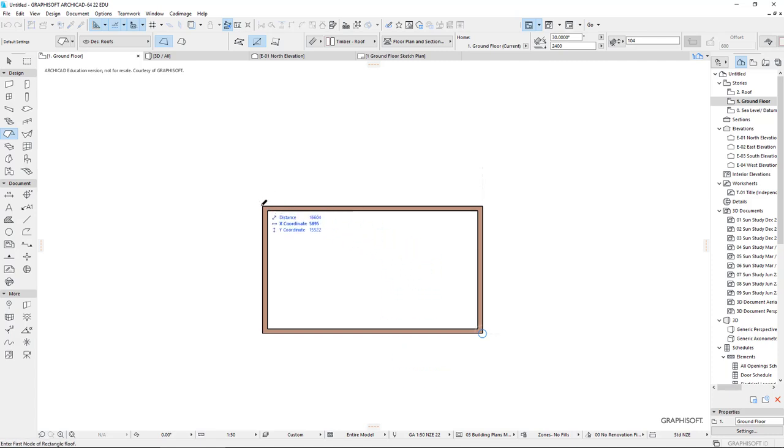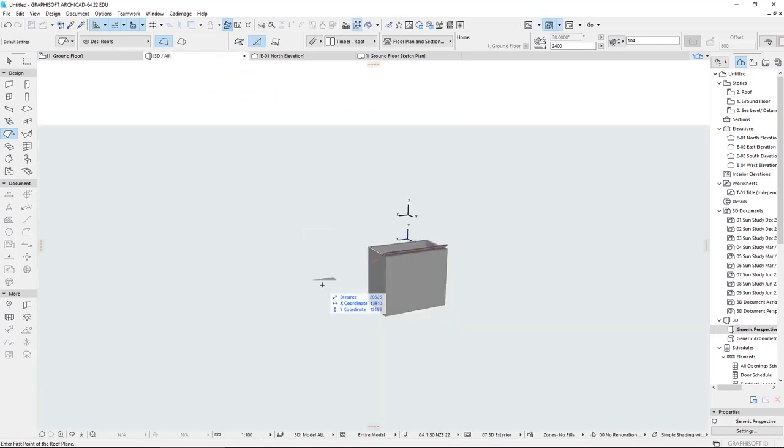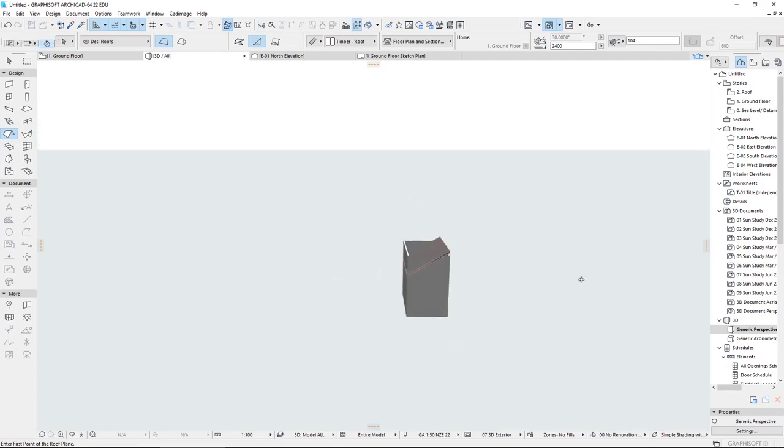And now I can click to start my roof, click there, click to finish, there, and it has created my roof. There it is, you can see it. Let's just turn our view around. So I'm using the shift plus my middle mouse wheel button. Now you do need to select your roof again. So let's select it. There's our angle 30 degrees. That should really be 8 degrees.